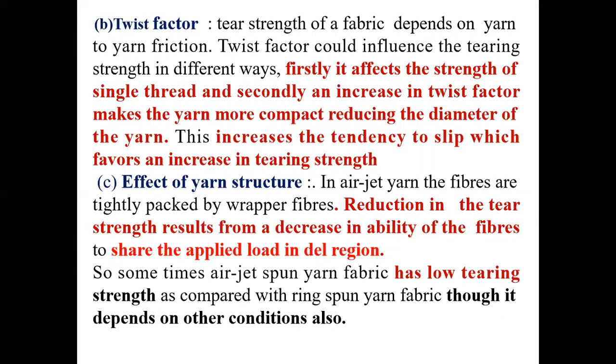Okay, so sometimes air jet yarn has lower tearing strength as compared with ring spun yarn, but it is not a hard and fast rule. It also depends on the hairiness, because if the hairiness is more, then the yarn to yarn friction will also be high.